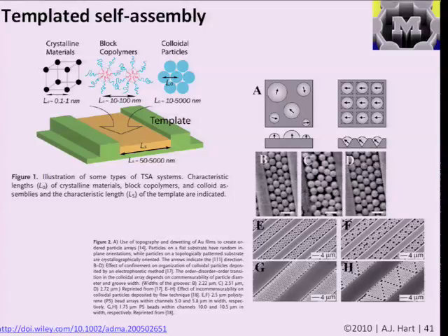So one example is what's shown here. For example, taking grooves etched in a substrate and introducing a solution of polymer microspheres, probably spheres in the 100 nanometer size range, to pack them into this trench. When the liquid evaporates from this trench, it's favorable for the particles to pack into these areas. And you can see the kinds of structures that can be made, in this case, by just controlling the width of the trench relative to the particle size. In some cases you get defects like this, and in other cases you can control the existence of defects to form more desirable structures like so.